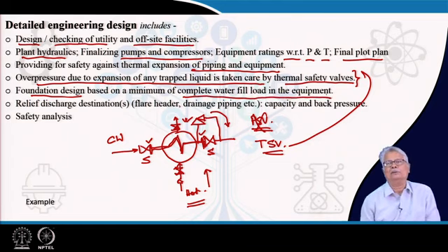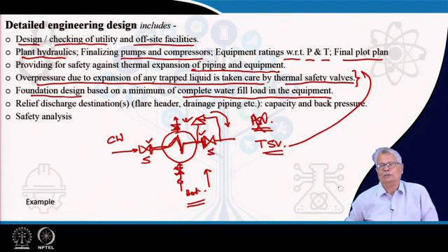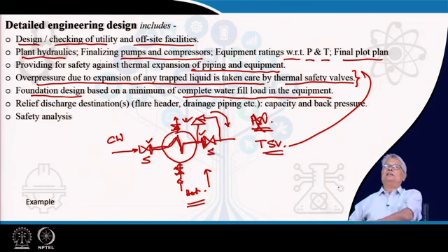For example, if you are talking about a distillation column, which normally will have a lot of vapor inside and some amount of liquid, the foundation load is designed not only on the weight of the metal and the weight of the liquid which it is supposed to carry, but even under emergencies it is considered fully filled with water. This is something that many do not, I will say, appreciate, because it often increases the foundation load bearing requirement quite a few times.